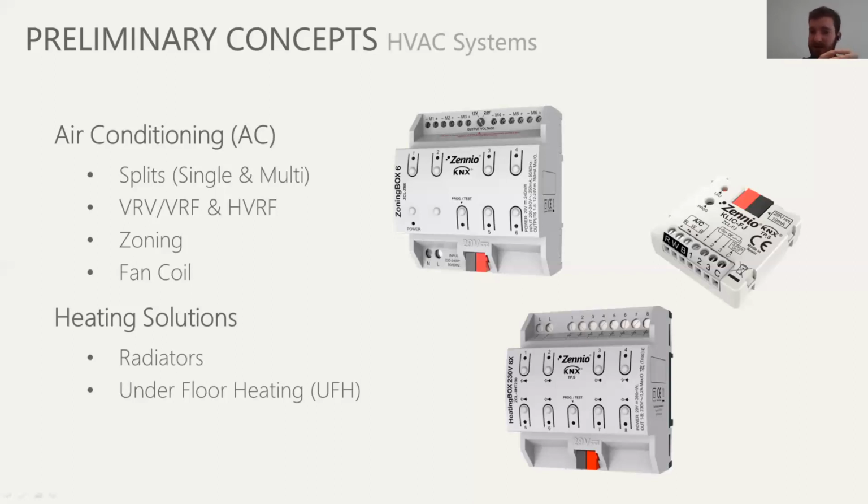While underfloor heating works because of the surface. The principle in underfloor heating is that you probably have it somewhere over 20 something degrees. You might want to keep that below 30 degrees. Depending on the country, there are a lot of regulations regarding underfloor heating, and there's a maximum temperature that changes in every country. But the principle of working is a very big surface and a very small temperature difference. So the exchange of temperatures is provoked by the big surface rather than a big temperature difference.